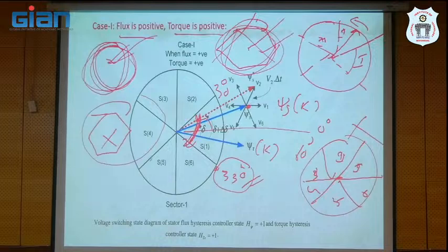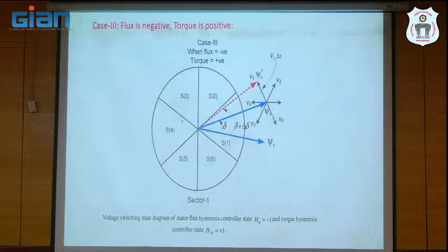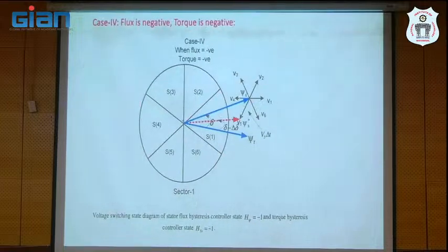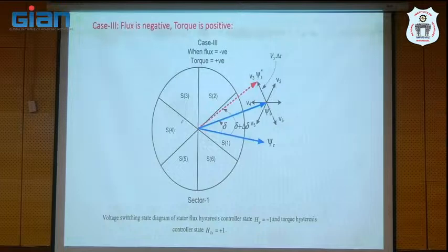So while defining the sector number, where the reference point is, is so important. If you take the reference point from 330 degrees, the advantage is the net flux becomes a circle. Otherwise, it will go in hexagon fashion, right? If sufficient time is there, I will show through simulation so that you will get more clarity. So these are all the various examples.